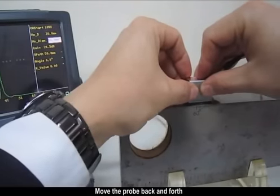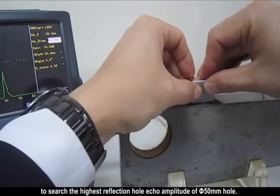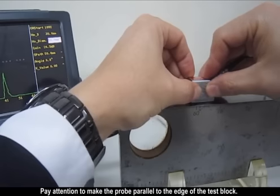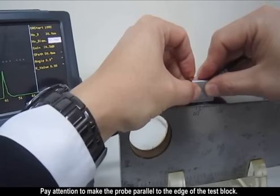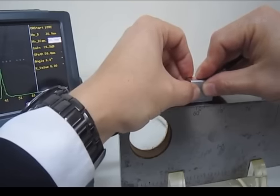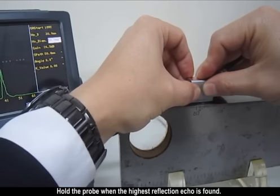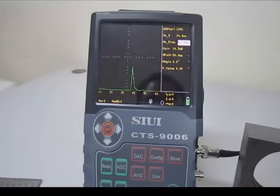Move the probe back and forth to search the highest reflection echo amplitude of the Φ50 mm hole. Pay attention to make the probe parallel to the edge of the test block. Hold the probe when the highest reflection echo is found.